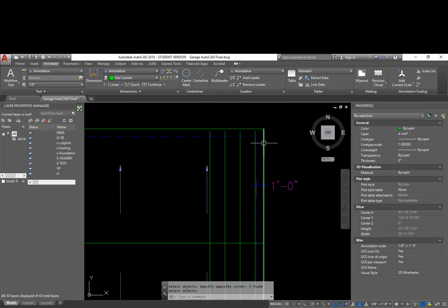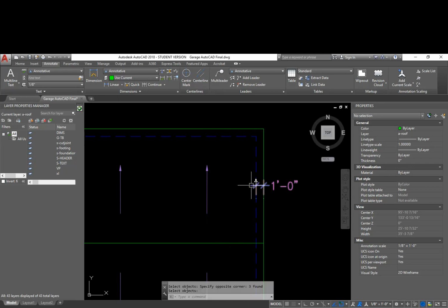But it basically extends out past, and this would be a kind of a weak component because it's all just hanging out there being nailed back into this last truss. So whenever I start laying my sheathing, my 5/8 inch sheathing, it would lap over top of this, giving it some additional strength. So I just wanted to point out that this is called the rake. This is just the tail of the truss overhanging here. Both of them are called overhangs.